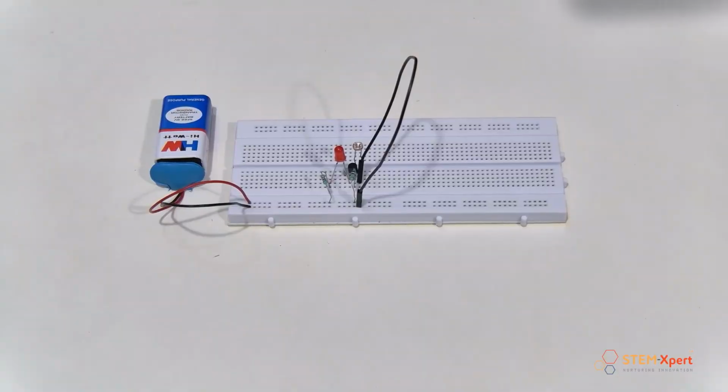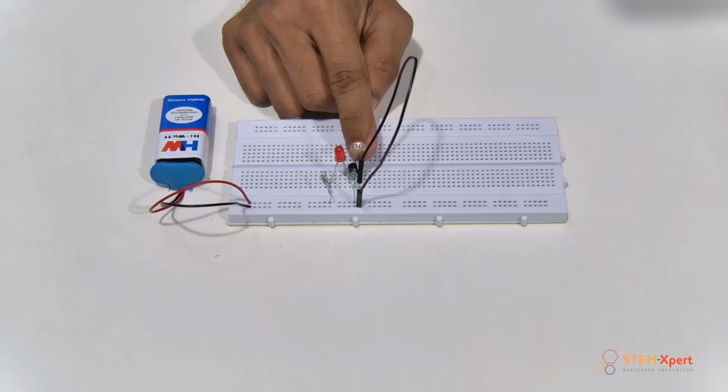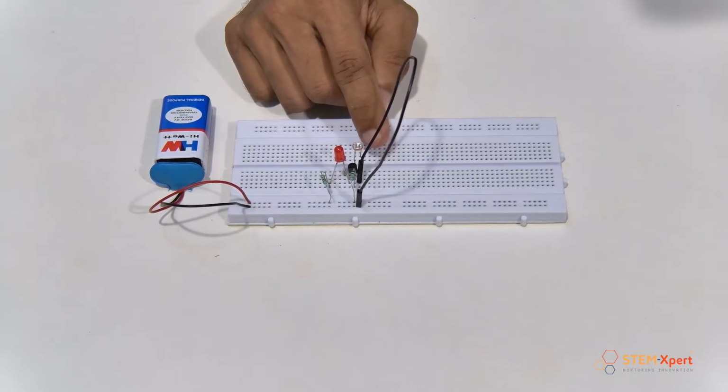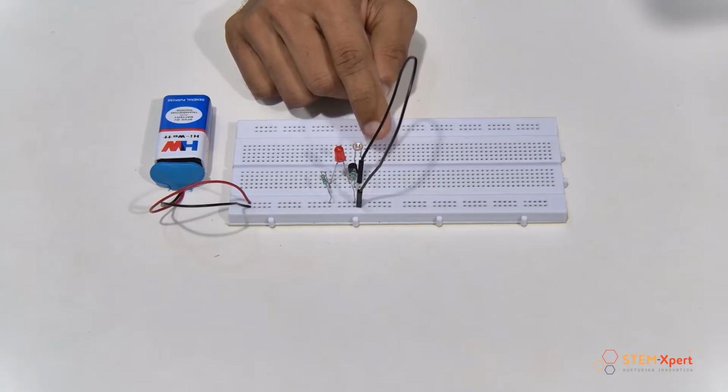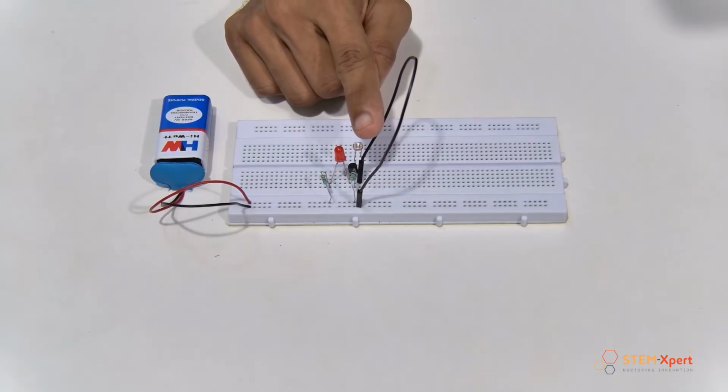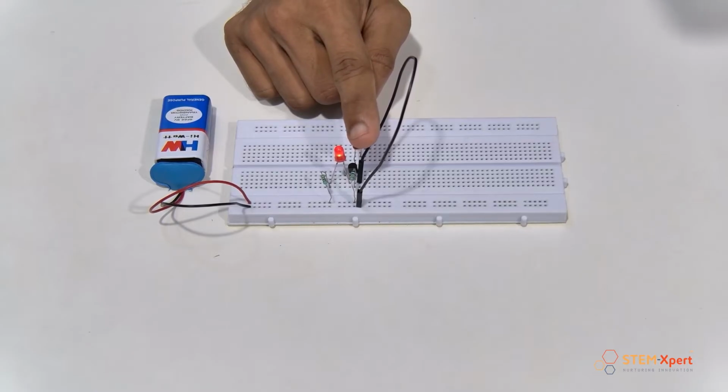Before we start our session, let's see how it works. As you can see, this is our automatic street light circuit. Here, the LDR detects darkness as night mode. Now you can see the LED is turned off because the LDR detects it as light mode. So when we create dark mode on the LDR, as you can see, our LED turns on. When I remove the hand, that means we create light mode again by means of this LDR resistor. Then automatically our LED turns off.